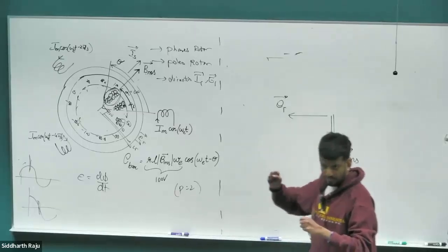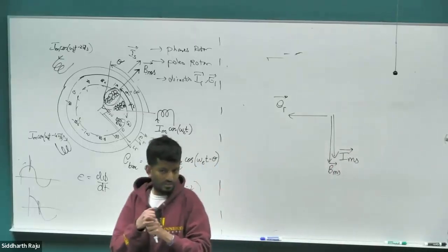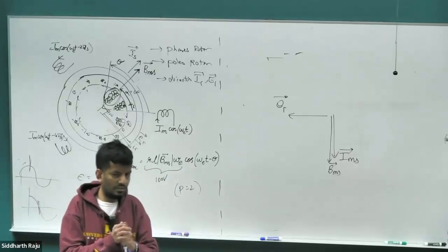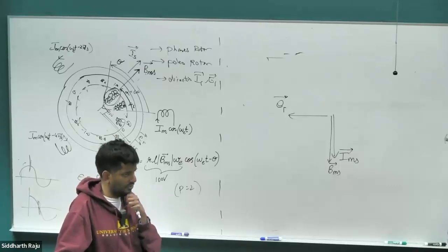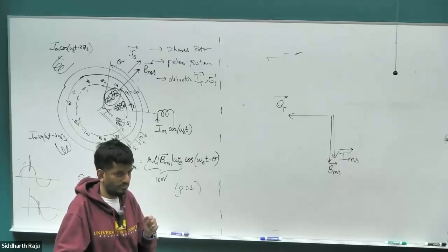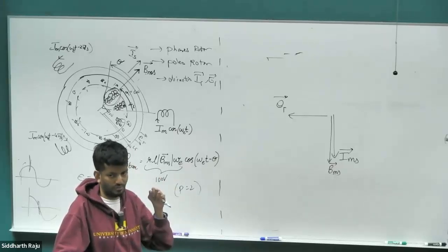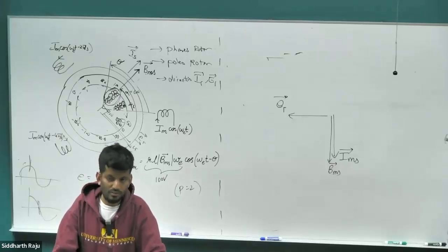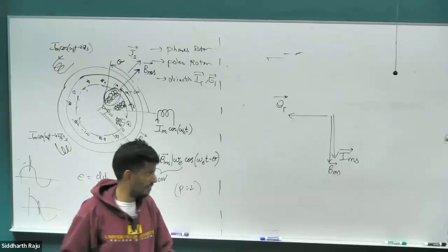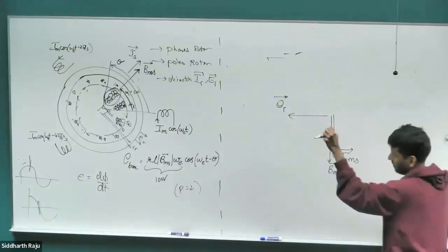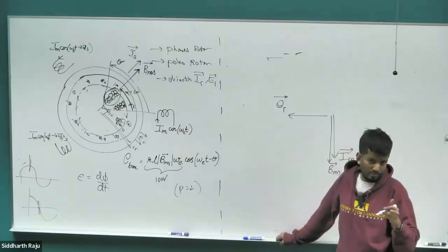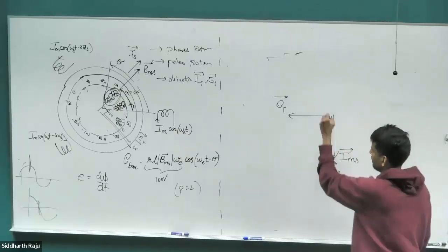Where is the rotor current space vector going to be? What will be the direction of the rotor current space vector? Let's start out with the simple case. If the rotor was purely resistive, where will the rotor current space vector be? Same direction. And if there was some inductive load, 90 degrees. Right? A combination of inductive and resistive, probably some alpha.